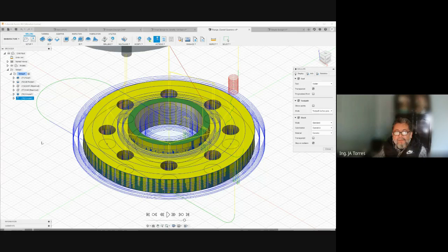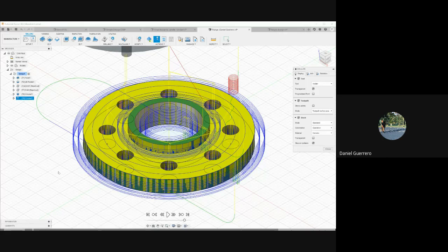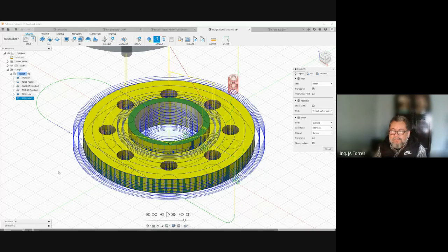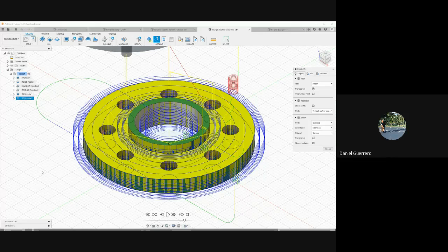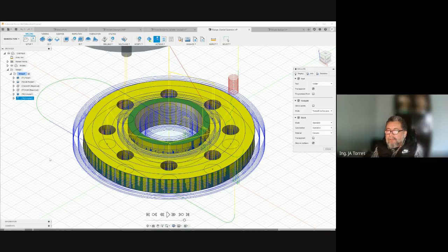Okay, you selected molybdenum steel because you want to use this piece in contact with water, I think. The stainless steel, yeah, with molybdenum. Well, that's the main reason for stainless steel. As you know, the water oxidizes the piece, and the 316L stops that corrosion.